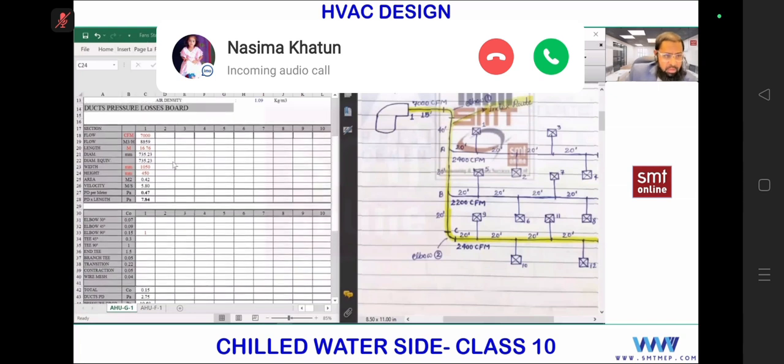Okay. Next, A to B. I'll copy this format to copy the formula. Copy, here paste. Now for A to B, can you find out the CFM online? Yeah, 2,400. No, for A to B it is 7,000 minus 2,400, 4,600, right? 4,600. Next, length. Length is 20 feet only. 20 feet, convert into meters: 6.09.